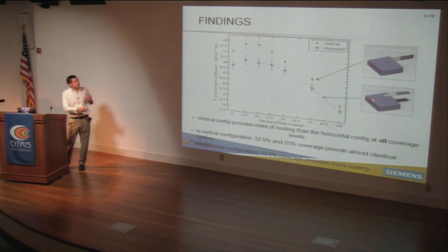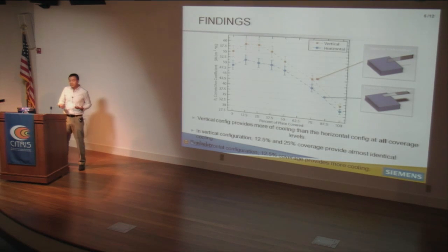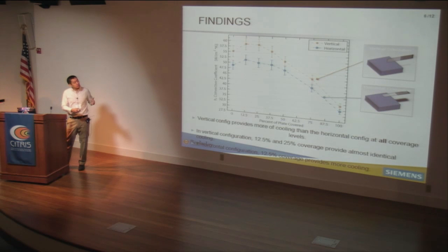In the case of vertical and horizontal configuration, the vertical configuration gives us a higher cooling effect than the horizontal. It intuitively makes sense, considering this flapping scenario, you are getting a bit of symmetric cooling in these two directions. In the case of a horizontal scenario, you're not taking advantage of some of the cooling that's occurring above the fan.